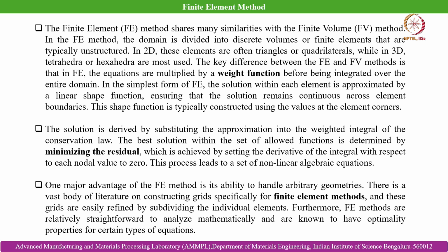This process leads to a set of non-linear algebraic equations that we subsequently solve by matrix algebra, and then we basically achieve the value of the particular primary and secondary variables at each nodal point within the finite element, and also thereby within the entire domain we can achieve the distribution of these primary and secondary variables of interest, for which we are basically solving the set of finite element equations.